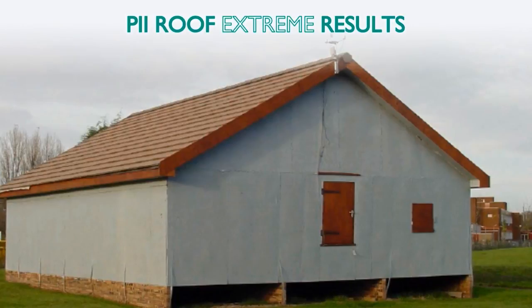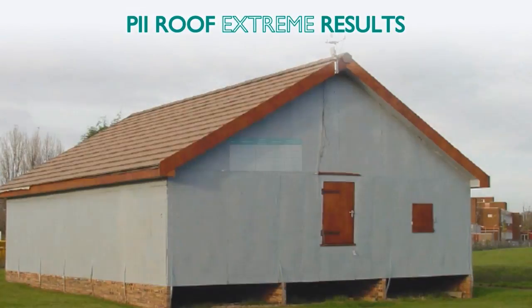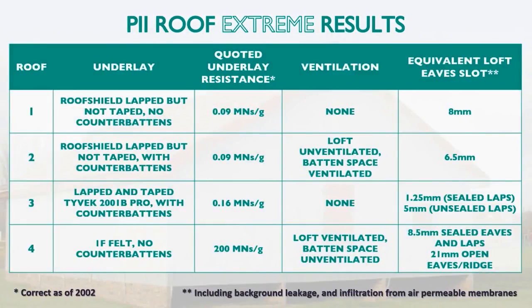The aim was to test and model the performance of different types of LR underlays and compare these results to conventionally ventilated roofing. A variety of test rigs were used to simulate conditions in a variety of roofs. The 4 test cases are shown here, and prior to testing all 4 test rigs were pressurised to determine the equivalent ventilation openings that would be necessary to replicate the air leakage characteristics of an unventilated roof.